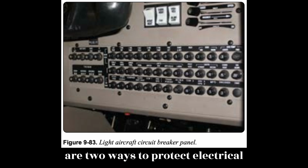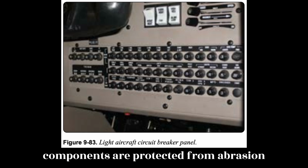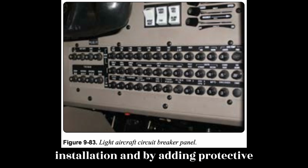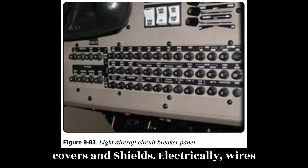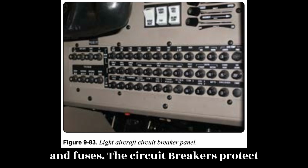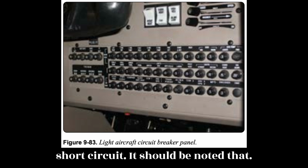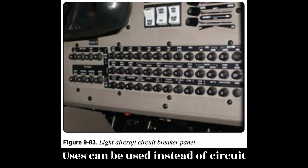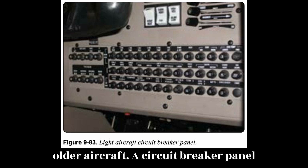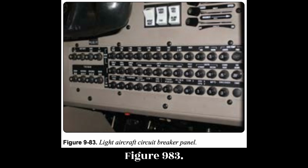There are two ways to protect electrical systems from faults, mechanically and electrically. Mechanically, wires and components are protected from abrasion and excess wear through proper installation and by adding protective covers and shields. Electrically, wires can be protected using circuit breakers and fuses. The circuit breakers protect each system in the event of a short circuit. It should be noted that fuses can be used instead of circuit breakers. Fuses are typically found on older aircraft. A circuit breaker panel from a light aircraft is shown in Figure 9.83.